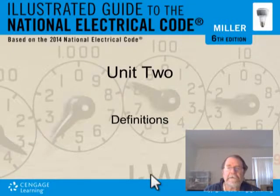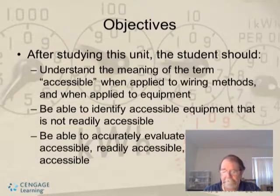We're talking about definitions today. The objectives of this course are basically, after studying this unit, you should be able to understand the meaning of the term accessible when applied to wiring methods and when applied to equipment. You should be able to identify accessible equipment that is not readily accessible, and you should be able to accurately evaluate a location as accessible, readily accessible, or not readily accessible.